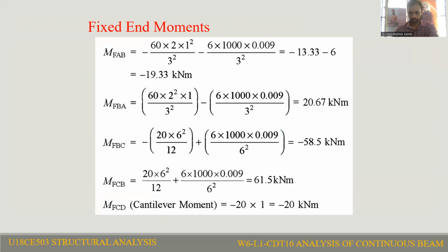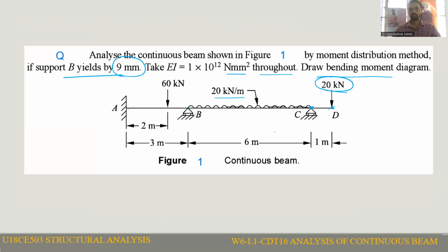Okay. So before going to the problem, I'll write the step by step procedure here. First step, you have to calculate the fixed moments. Second step, you have to calculate the distribution factors. Third step, you need to draw the distribution table.